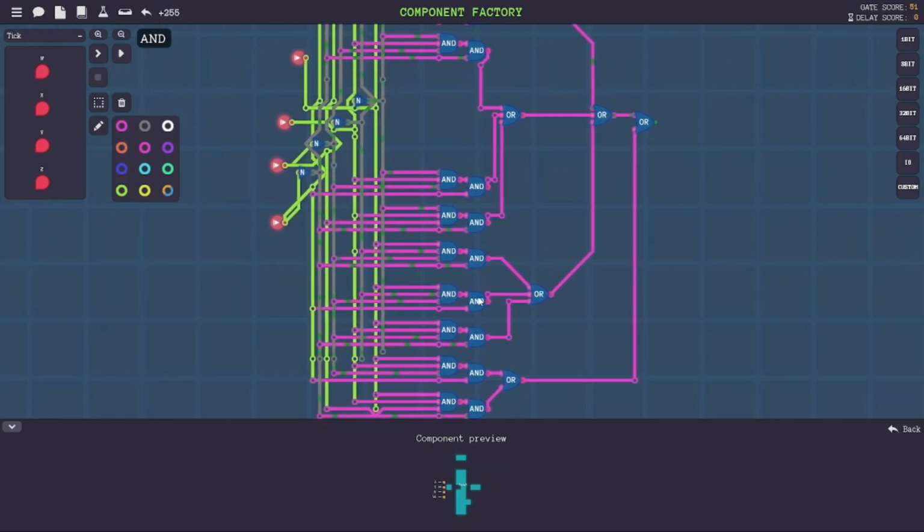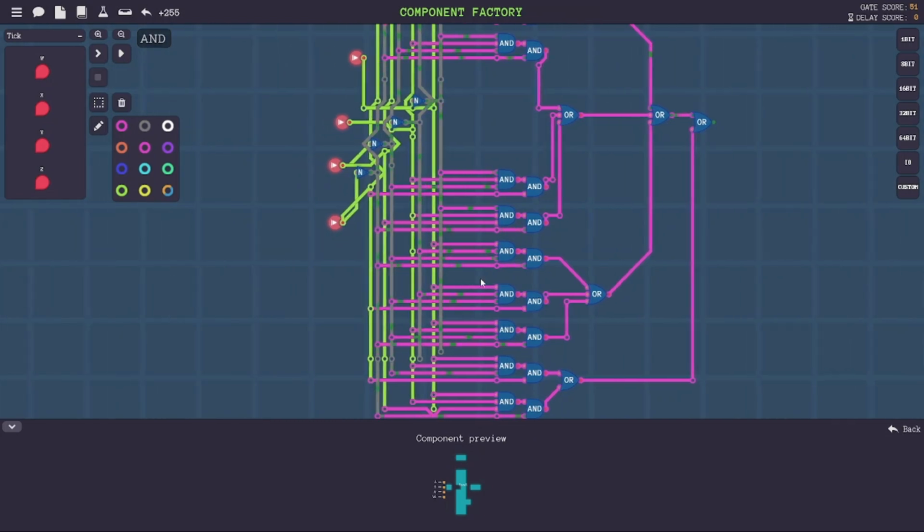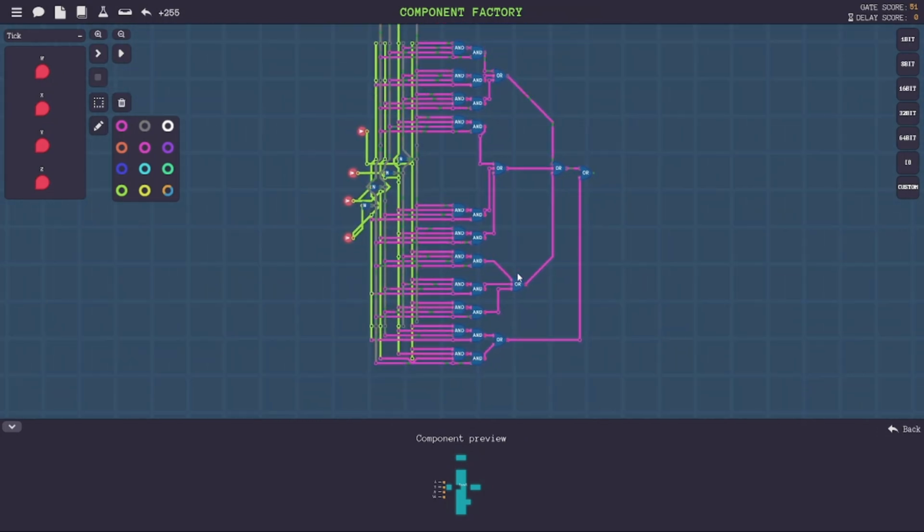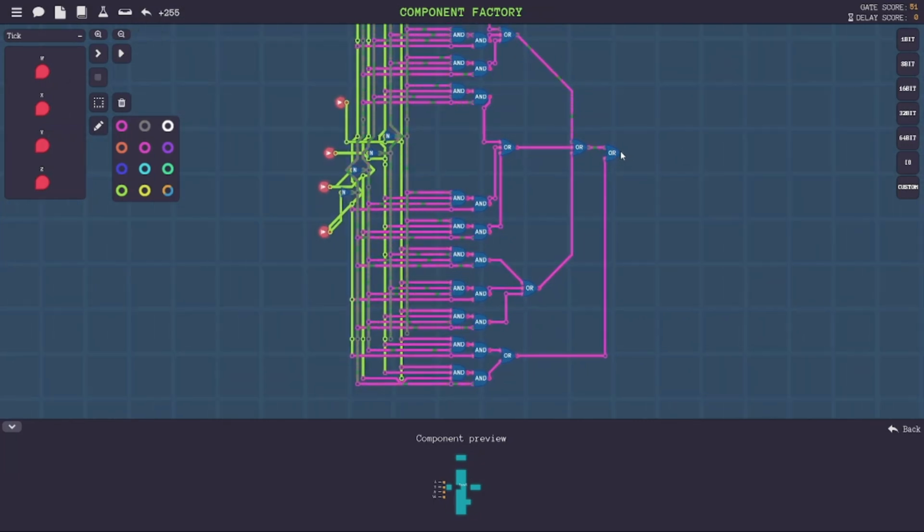This is one of the functions that we will hopefully be optimizing and simplifying its Boolean expression. Here you have the function, here you have the input, and here you have the output, which is this small light, either green or red. When you change the input, for example when you have one, as in binary, then two, then three, the output is off. When you have two, it is on. So these are the minterms of the function, and you see this is a circuit that's actually implemented using the Boolean expression.